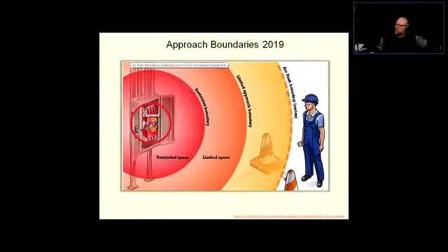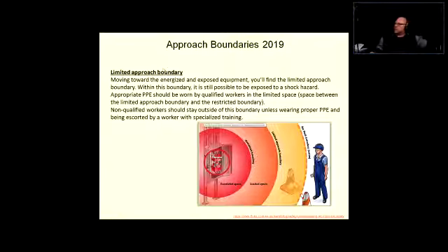All right, arc flash boundary, then limited approach and restricted boundary. So we're talking about limited. Moving towards the energetic, you will find a limited approach boundary. Within this boundary, it is still possible to be exposed to the shock hazard. Appropriate PPE should be worn by qualified workers in the limited space between the limited approach boundary and the restricted boundary.